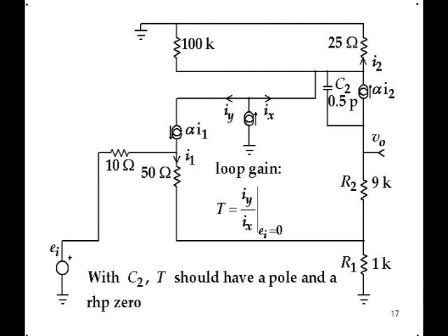So you end up with a flat gain at low frequency and another flat gain at high frequency with a full phase inversion in between. So you get a pole from the capacitor at low frequencies, and the zero that you get at high frequencies is a right half plane zero, an RHP zero. So the asymptotic phase angle is 180 degrees from what it was at low frequency. So if you check that out by injecting a test signal and see what the answer is that you get, here's the method for doing it.